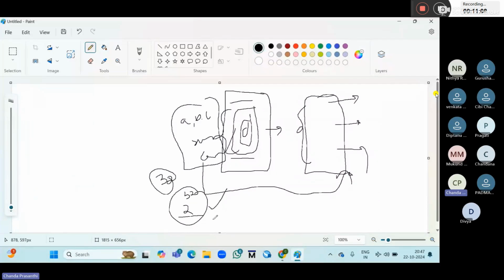Here A, B, C are three inputs, just single bits, so we can create those very easily. But 2 power 32 combinations we cannot verify easily, right? So to verify 2 power 32 combinations, we divide them into test cases. And not only 2 power 32 combinations: inside the specification there are a lot of control signals and different bus signals. Suppose there will be write and read signals, address signal, data signal, 10 different data signals or 10 different addresses. There will be a lot of signals, right?